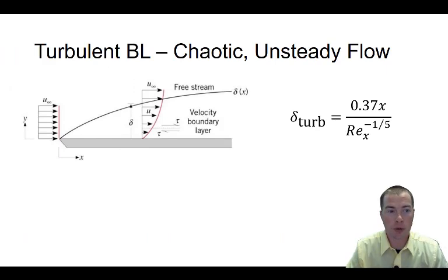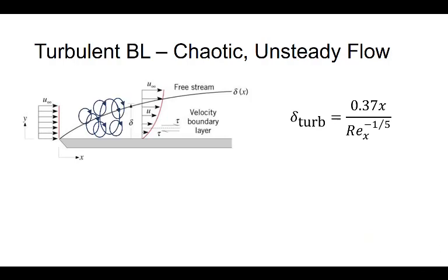In a turbulent boundary layer, the flow looks very different. Imagine that the boundary layer is tripped at the leading edge to become turbulent immediately. This can be accomplished by adding elements that stir the fluid up near the leading edge. In a turbulent boundary layer, additional motion is achieved in the vertical direction due to swirling eddies.